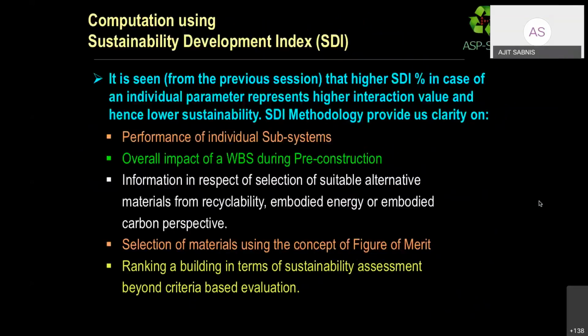Now, we have talked about how to evaluate embodied energy and embodied carbon, taking the entire life cycle of a building into consideration, and then computing or analyzing a building using the Sustainability Development Index. We also saw in the last session that a higher SDI percentage for an individual parameter represents a higher interaction value and hence lower sustainability.